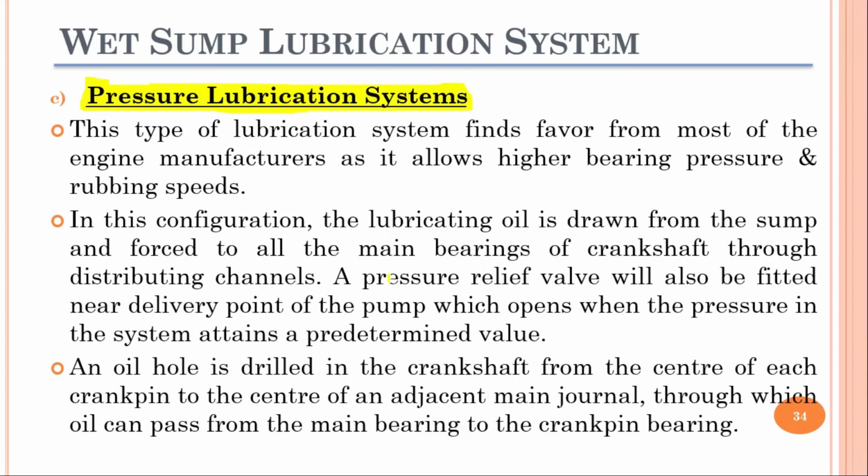So this type of lubrication system finds favor from most of the engine manufacturers. As I mentioned earlier, these types of lubrication systems are being used most commonly by the engine manufacturers, as it allows higher bearing pressure and rubbing speeds. So in this configuration, the lubricating oil is drawn from the sump and forced to all the main bearings of the crankshaft through the distributing channels. And we also have a pressure relief valve, which is being fitted near the delivery point